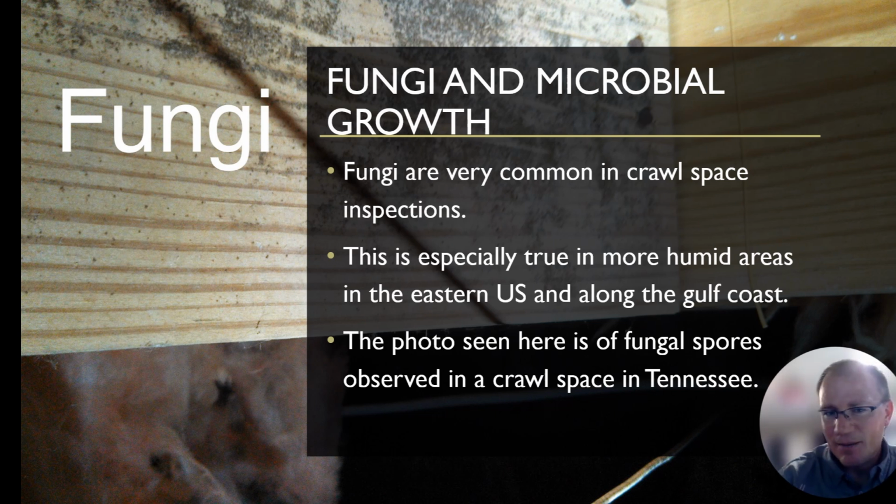Another interesting thing you're going to come across in crawl spaces is fungi and microbial growth. There's a lot that could be said about these things, and each state has a different idea of how they look at this as far as treatments, as far as what you need to write down on inspections. But I did want to let you know that fungi are common in crawl space inspections. This is especially true in more humid areas in the eastern U.S. and along the Gulf Coast and even in the Pacific Northwest.